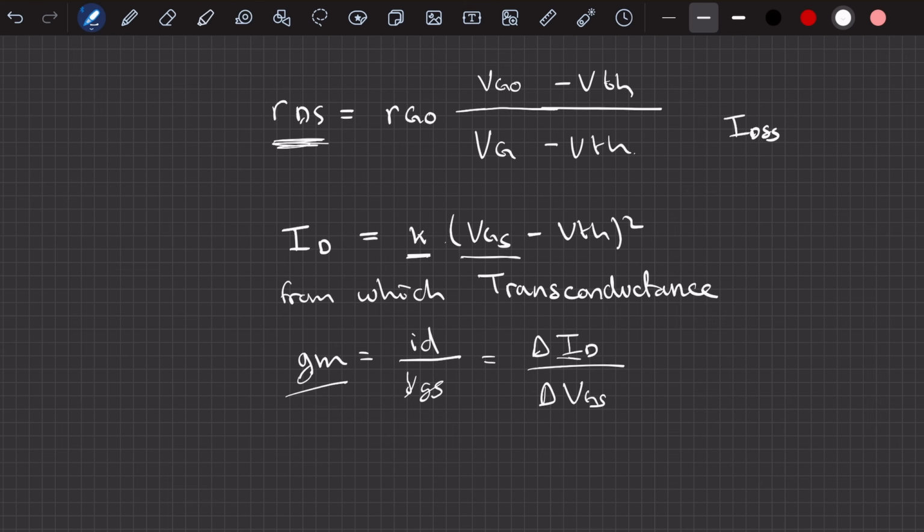It kind of tells you how strongly the transistor responds to gate voltage, as you can see from this side over here. And you've got the square law over here, which is implied in the question. A bigger K means the device can produce more drain current for the same gate-source voltage. I think the K is dependent on physical parameters, and this value is typically not listed in datasheets, as far as I know. So this equation obviously becomes a little bit harder to work with, whereas this equation doesn't have K, and it's probably one of the reasons why we're deriving it as well.